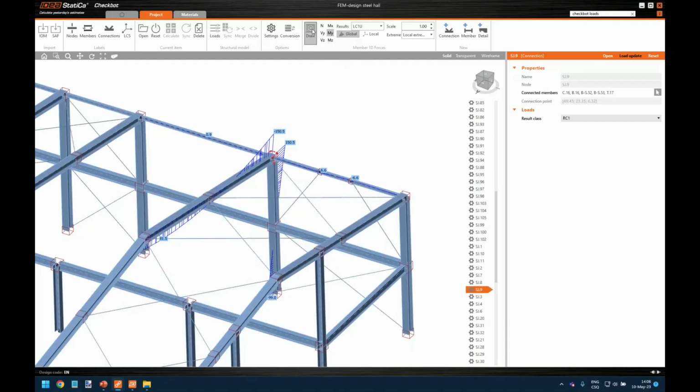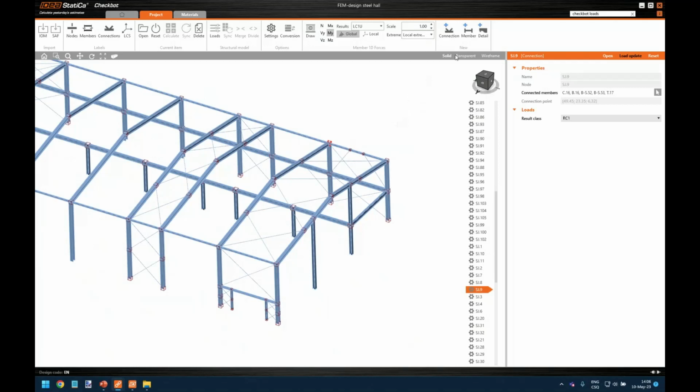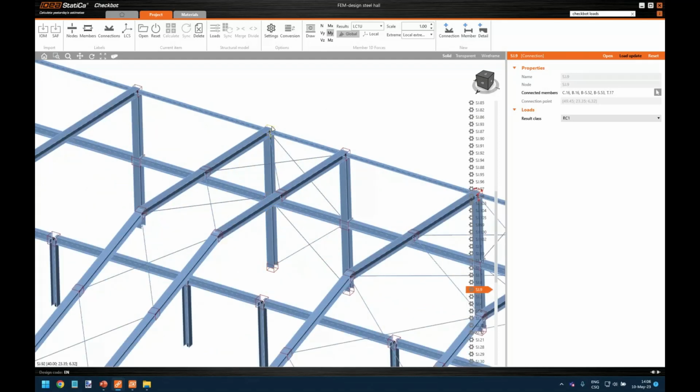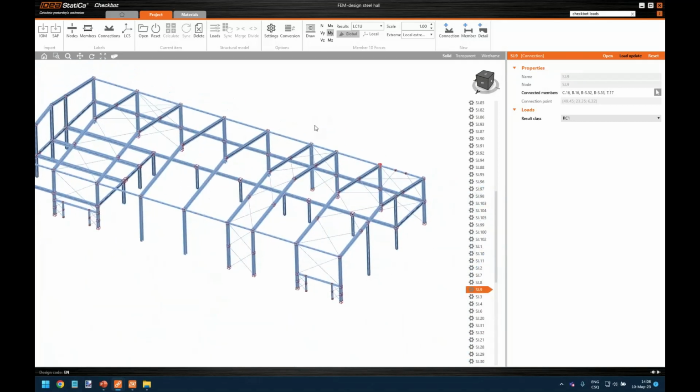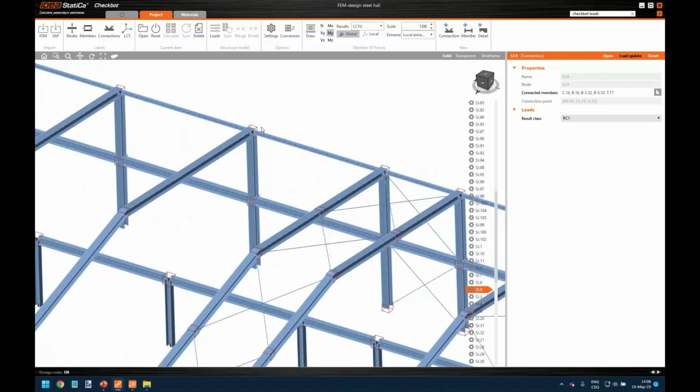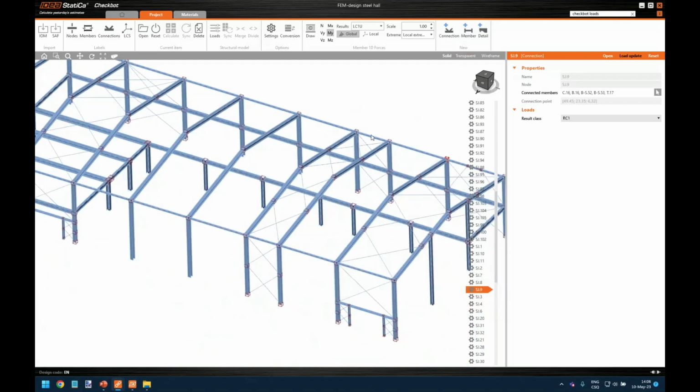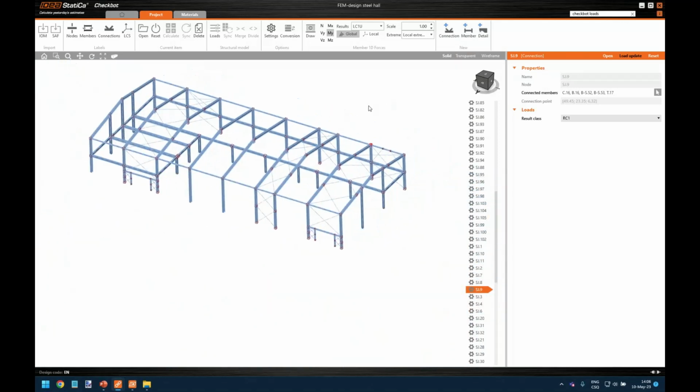If I go back to solid view and scaling and choosing if I want to load local extreme and so on. And these functions are here if, for example, you delete the node or you miss it from the data, you can add a node and build a connection based on the data of the members around it. So this is in the case you are missing something in the imported data, you can replace it.